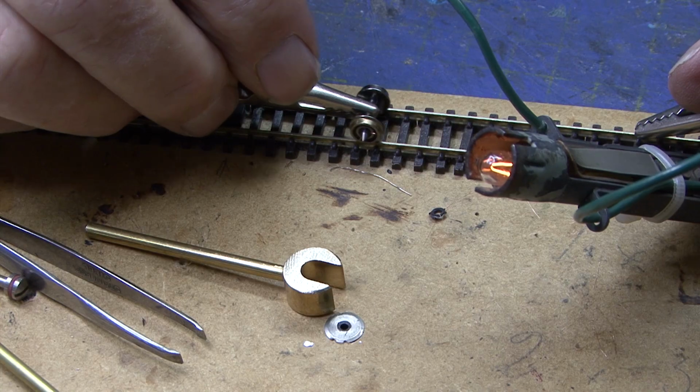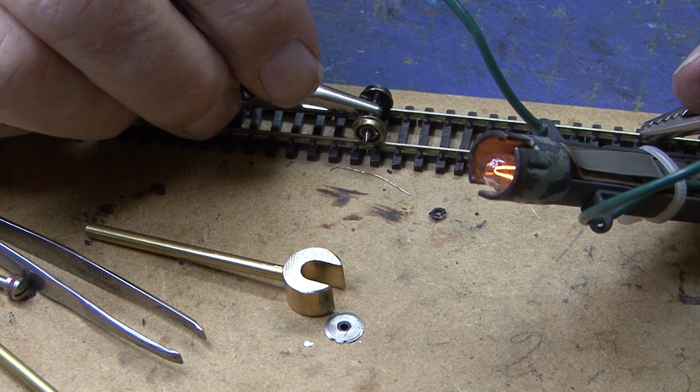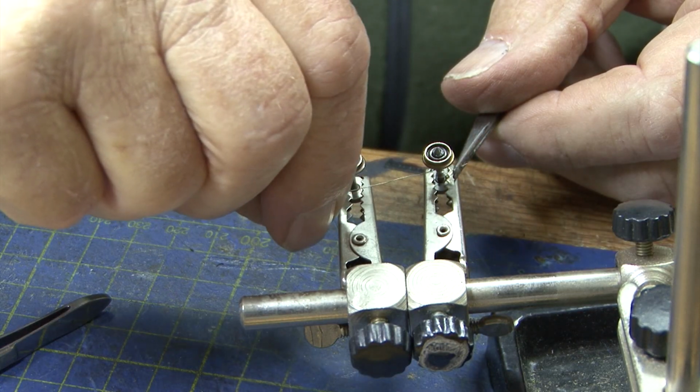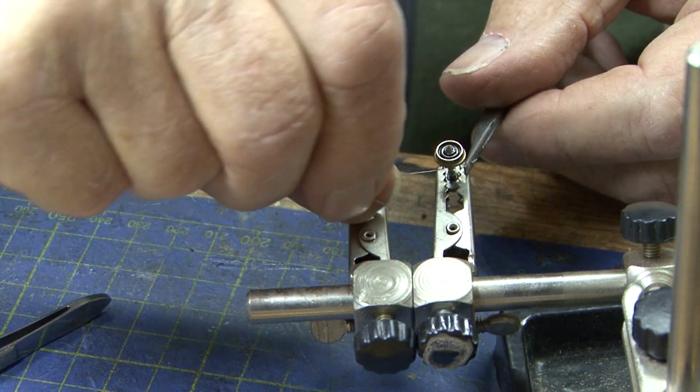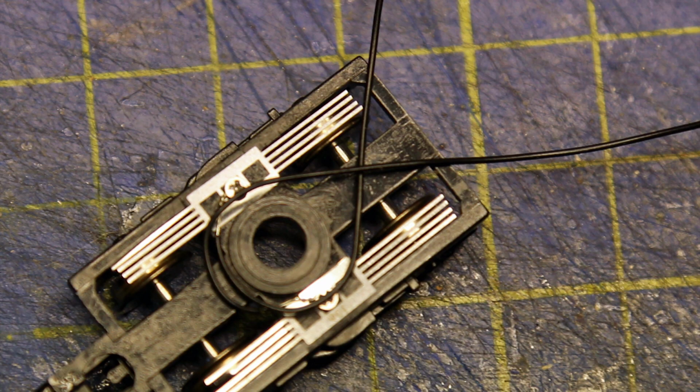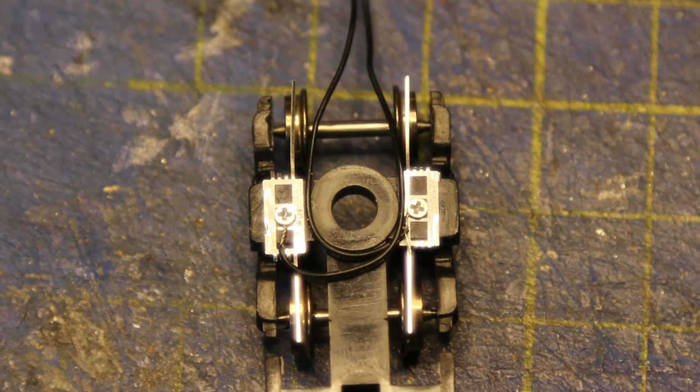And although I succeeded in making the axle live, the purpose-made pickup springs or my own wiring caused unacceptable resistance to movement. The time spent and the damage to several wheel sets, not to mention the resistance to movement, made it a non-starter. However, I did try again when I saw an idea of picking up the power from the wheels themselves, which was proving successful. Minimal resistance to movement and a live axle is not required.